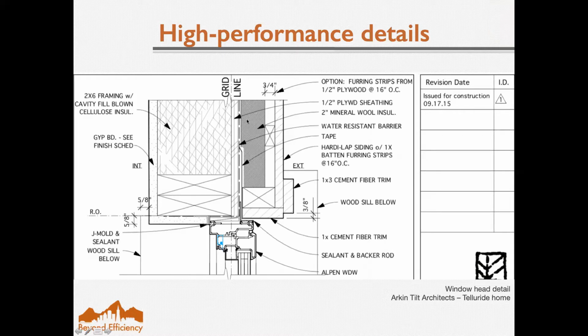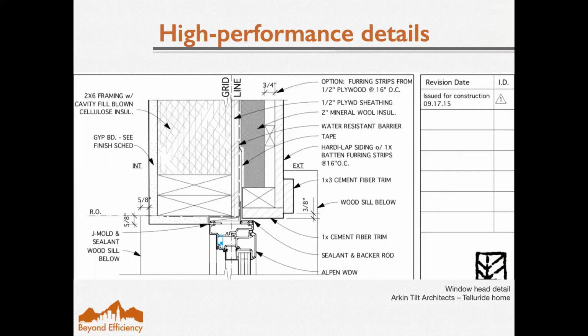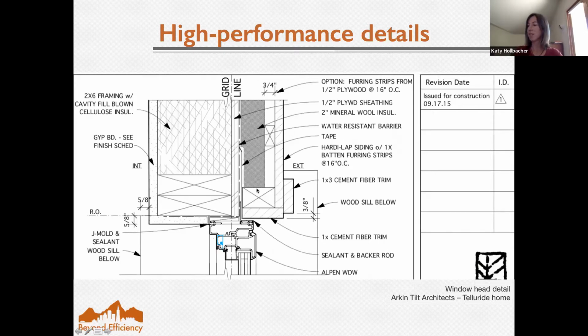So if you have continuous insulation outboard, it mitigates the thermal bridging and melting of ice on roofs and things like ice dams that you'll see in our cold climate. So yeah, this is definitely a concept we highly encourage.